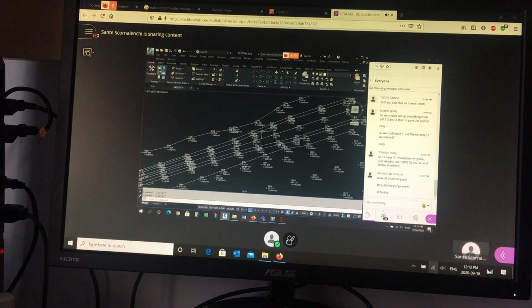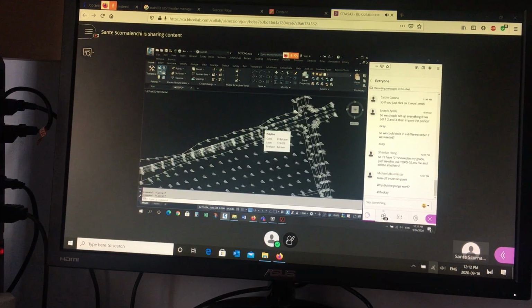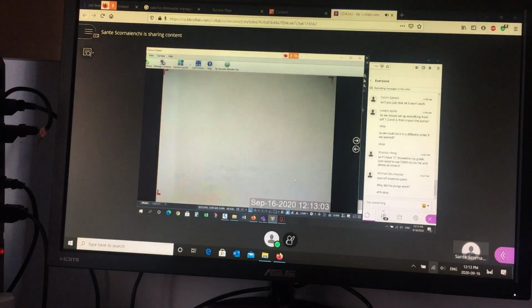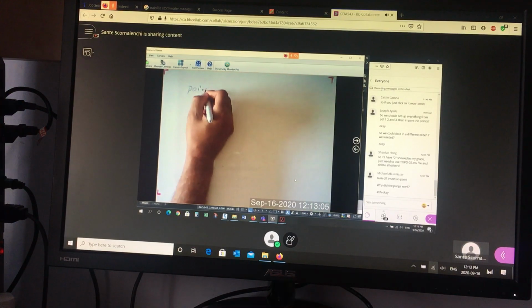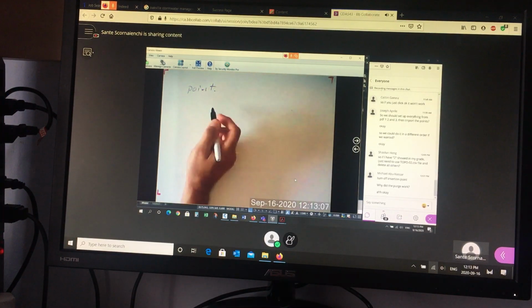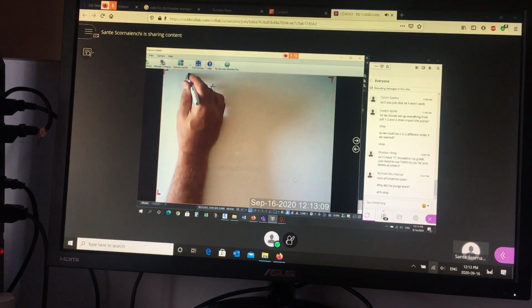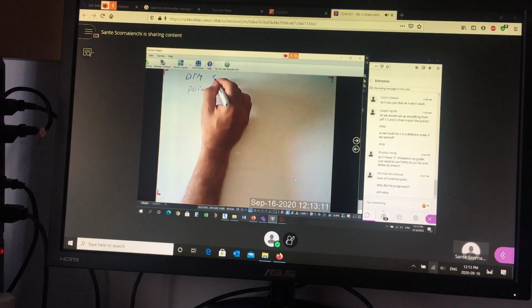Okay? These polylines actually represent what's called break lines or fault lines. You might have heard these terms. A break line and a fault line can be used for the triangulation on a surface. So to create a surface, go back to here. To create a surface, you need point information. And you can create different styles for it and so on, to create a digital terrain model for a surface.